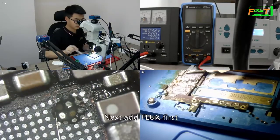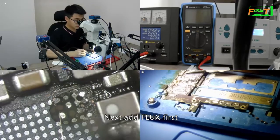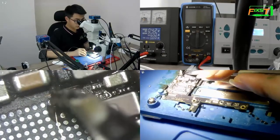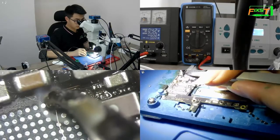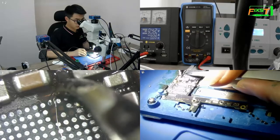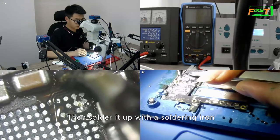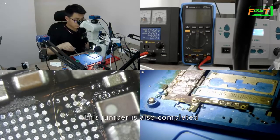Next, add flux first. Place the wire first. Then solder it up with a soldering iron. This jumper is also completed.